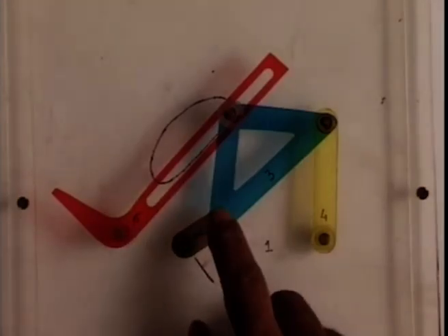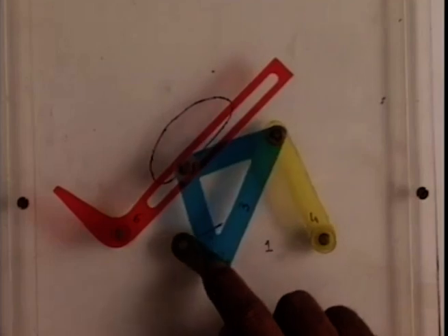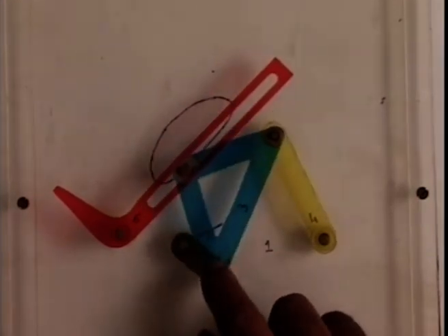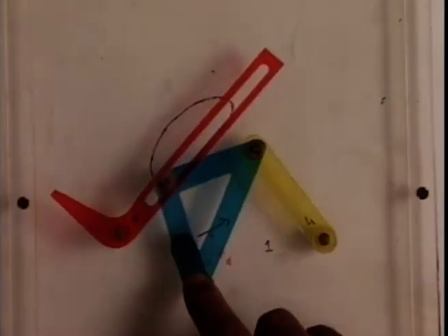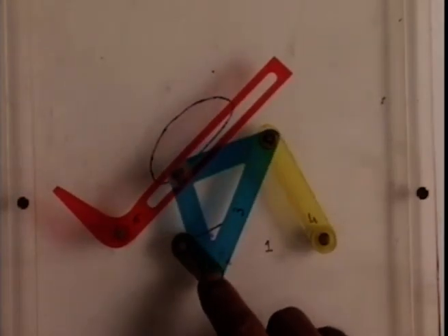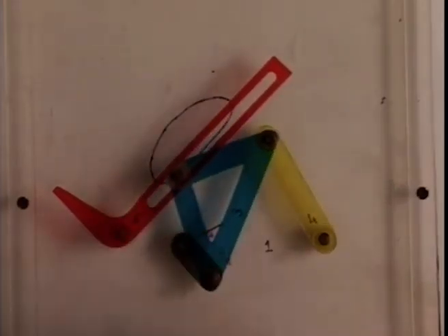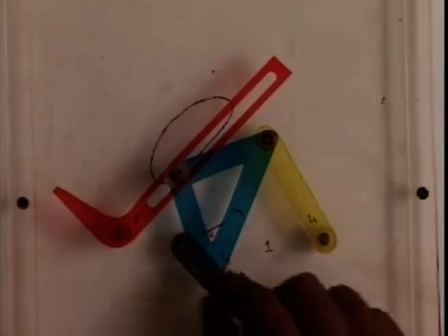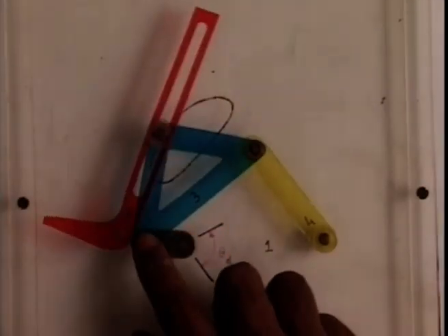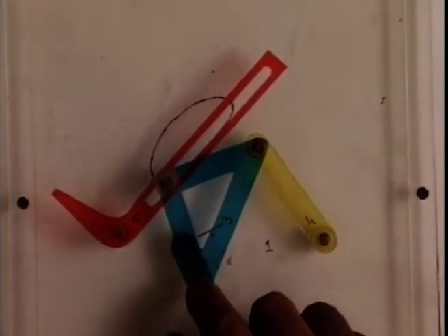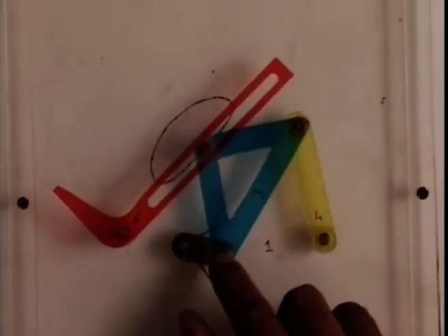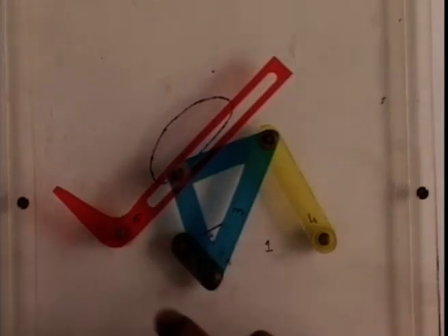and that is why we call it a dwell mechanism. The input link 2 rotates continuously, but during this movement of link 2, as we see, there is hardly any movement of link 6. Link 6 almost does not move. So link 6 undergoes a dwell, that is a rest period. So such a dwell mechanism is very useful for various applications. Now link 2, during this movement, as we see, link 6 moves, but during this amount of movement of link 2, link 6 hardly moves.